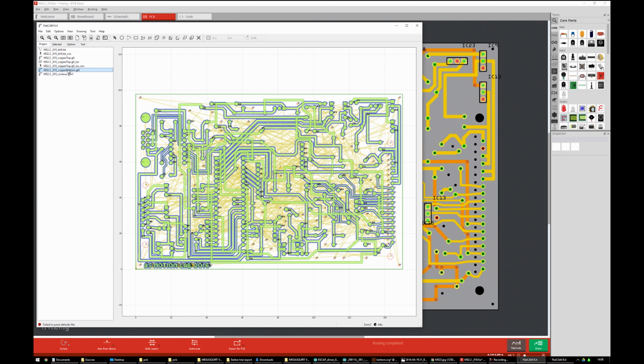So let's flip the copper board, the bottom copper. Select it, tool, select what you want to flip, select the axis, find axis locations, the box, and then we use the contour as the flipping guide. Mirror object.